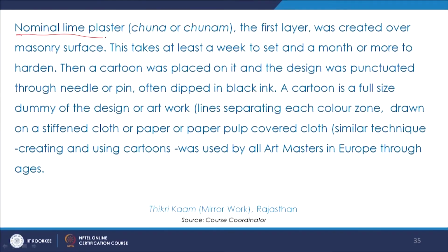Okay, so this is a small discussion on how this lime plaster that we saw, with which the mirror work was done, is prepared, and this is quite important, so I would like to just explain this. So nominal lime plaster, which was called chuna or chunam. Here what happens, the first layer, it was created over a masonry surface. This takes at least a week to set and a month or more to harden. Then a cartoon was placed on it, and the design was punctuated through needle or pin, often dipped in black ink. So this would give us the sort of design that is required.